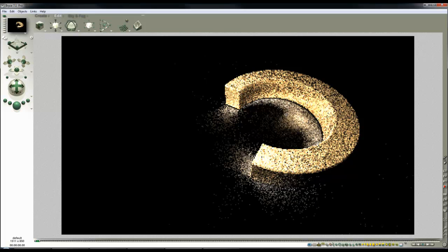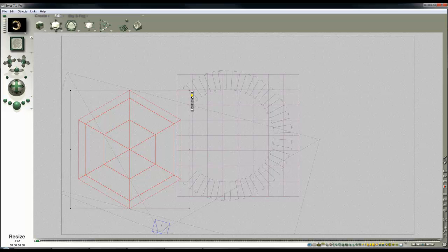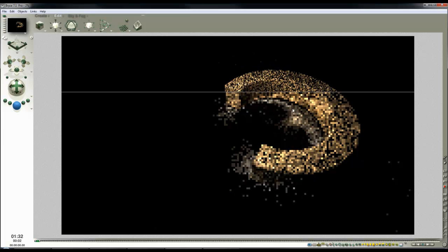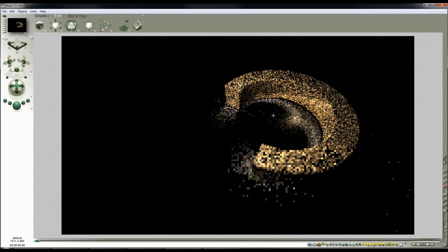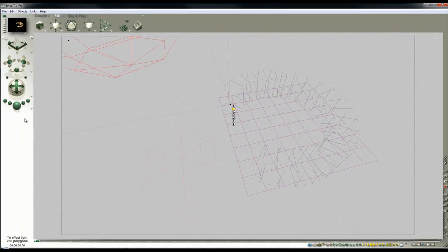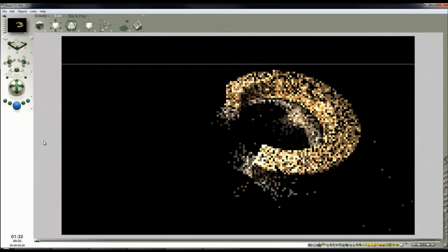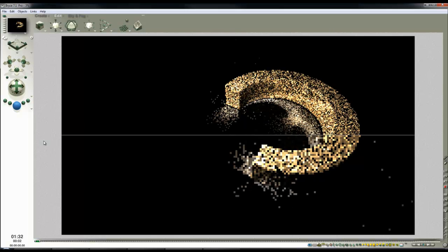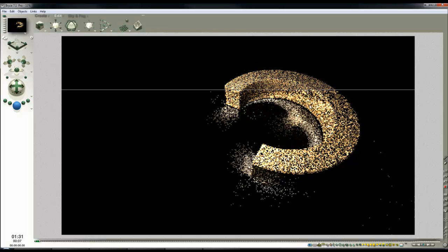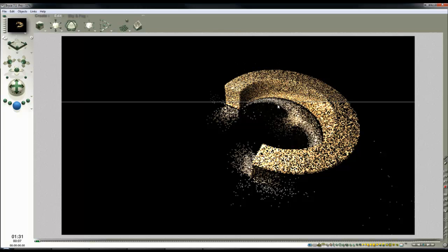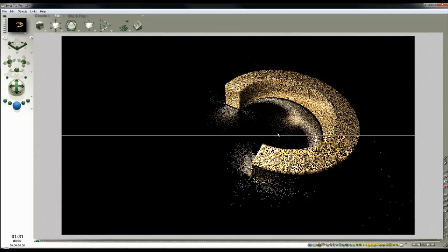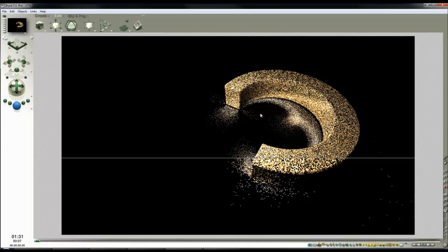If I want to sharpen that effect, I need to reduce the size of the light source generating it, because it's the surface of the light source. So you can see the effect is a bit sharper now, but weaker, so I can modify this to produce yet more light for the effect. But the drawback of this is that as the light source gets smaller, the noise level rises, because the difference between where this is getting the effect from the light source, which is very bright, and the environment, which is very dark, means that sometimes it sees the light source, sometimes it sees the dark, and then you get this high noise. So there's a payoff there between the two.